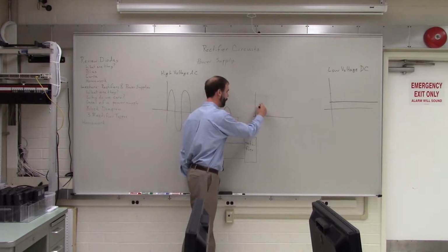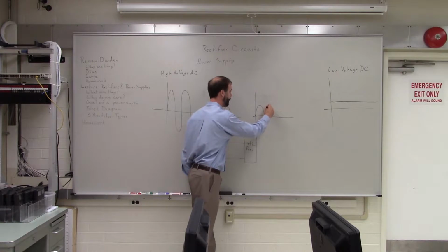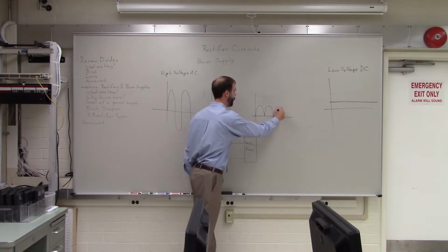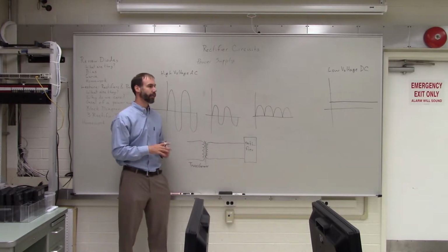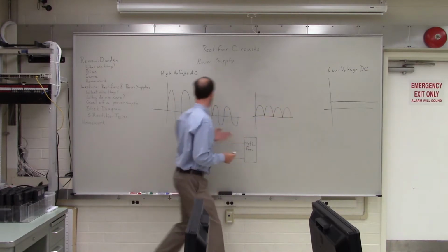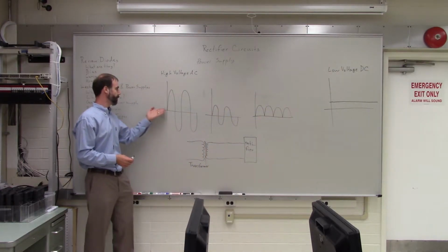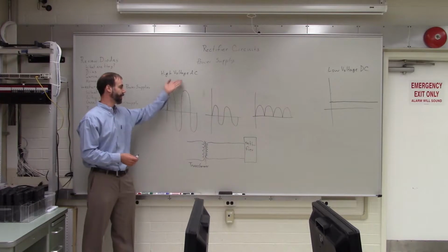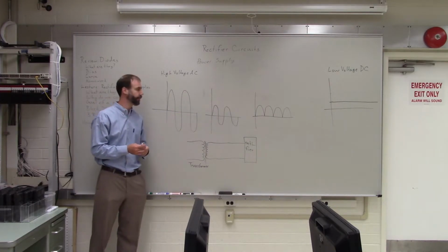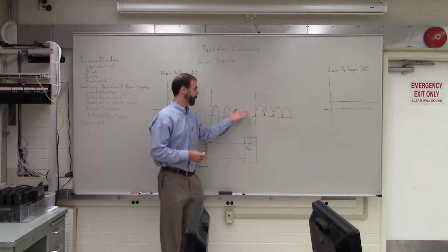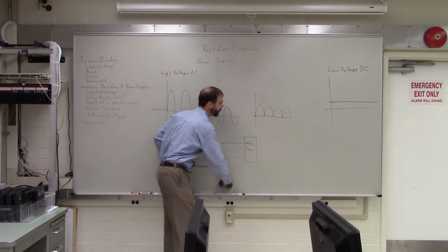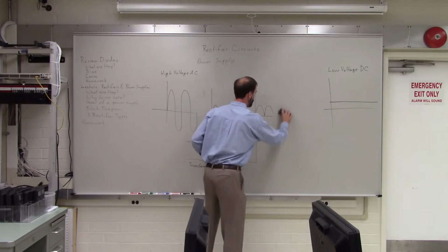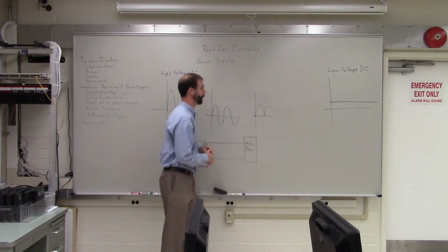So we'll see that different rectifiers give us signals that look a little bit different, but in general, all rectifiers give you a signal that's only positive coming out. Right. AC goes positive half the time and negative half the time, and it goes back and forth like that. Rectifiers take that signal and turn it into something that's only positive. Just save a little bit of room here.